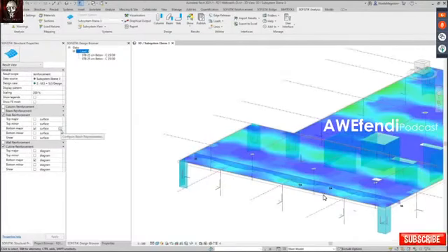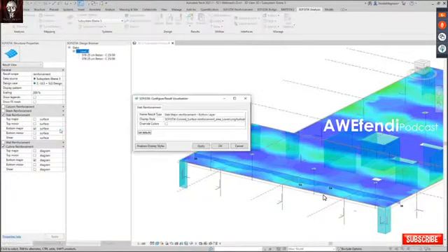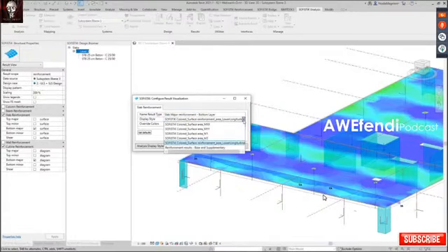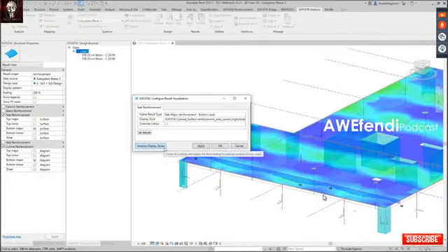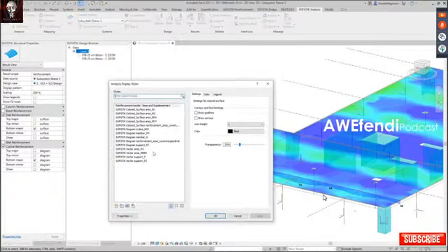And if I want to switch the color, for example, of my color map, I can go here and configure the result visualization. Here we are using the Revit analysis display style. So we already give some functionalities to check quickly and change the colors, but maybe it's smarter for you to go into the analysis display style dialog of Revit and also pre-configure some display styles.